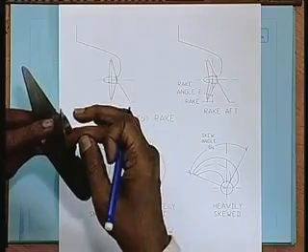It is not denied, but it is generally not there, because if you give a forward rake, the clearances reduce the way the propeller is fitted behind the ship. Skew is, if I take the propeller axis like this and if it is perpendicular to this, it is called no skew. So, there is another way to define this.